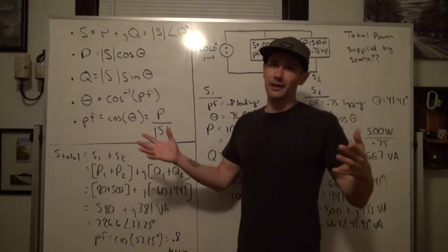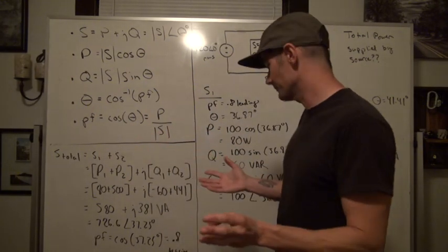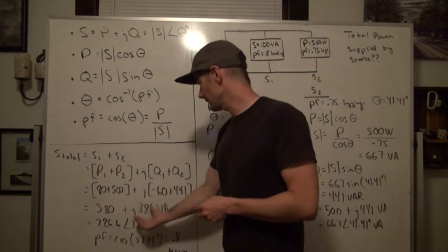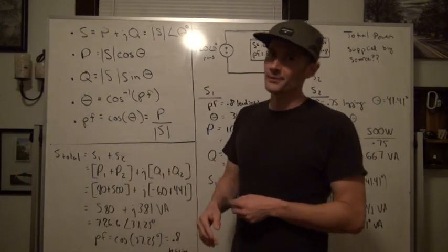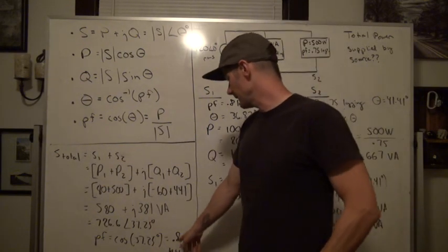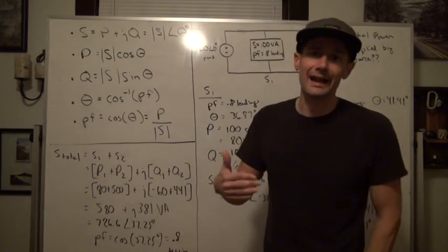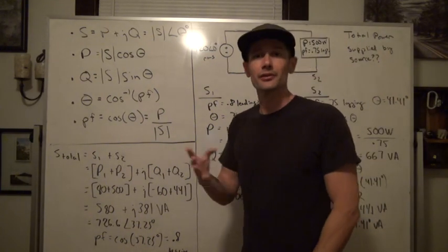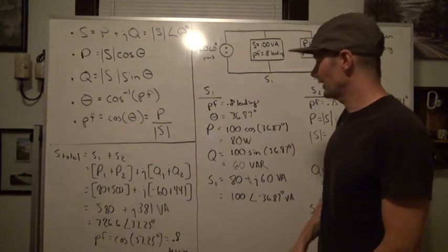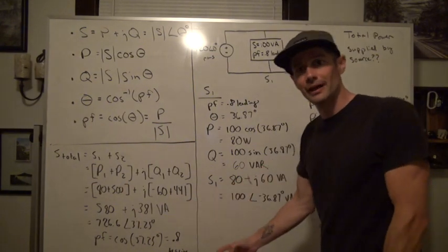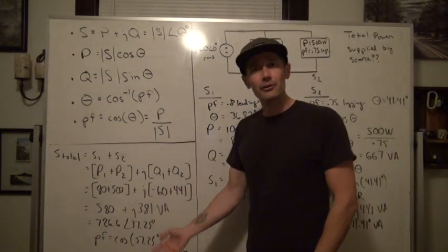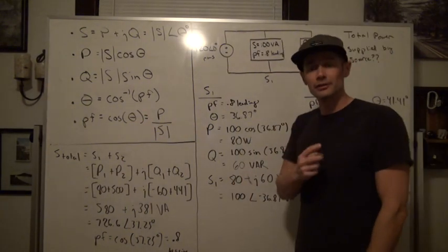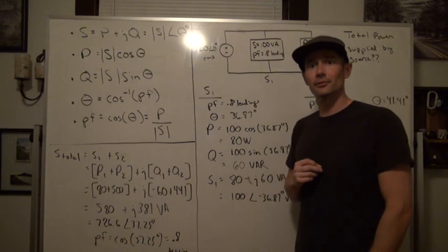But guys, do we have an efficient system? Is it efficient? We can obviously look down here at that phase angle, at that reactive power relative to the real power, and it's not efficient. We've got a power factor, that ratio, of 0.8 lagging. That is not what we want as an efficient system. We could easily decide that we want to bring that down by a certain amount of reactive power and then derive a capacitor. We could pop that onto the end of this if we want. You guys could do that because you've been doing that up until this point.